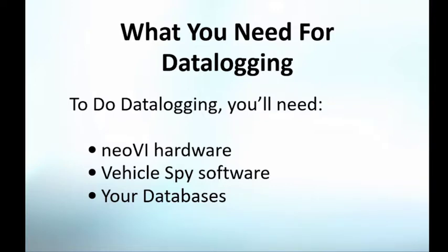And then your databases, that's not a hard requirement, but it makes the setup a lot easier. And what you would be using, let's say, a DBC file for, let's say you want to trigger off of a certain value. It's obviously a lot easier if you have the DBC file loaded because you can just double click on that value that you want to trigger off of without having to program it in.